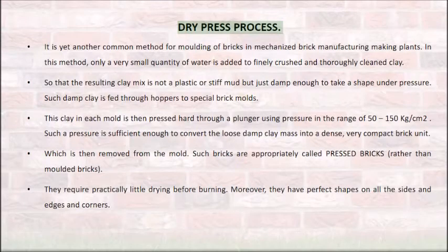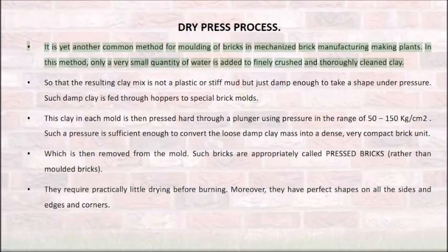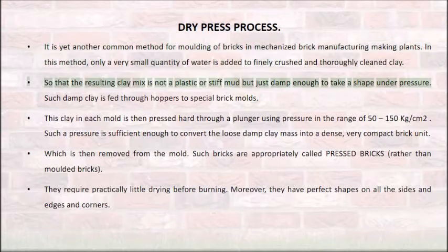Dry press process. It is yet another common method for molding of bricks in mechanized brick manufacturing plants. In this method, only a very small quantity of water is added to finely crushed and thoroughly cleaned clay, so that the resulting clay mix is not a plastic or stiff mud but just damp enough to take a shape under pressure.